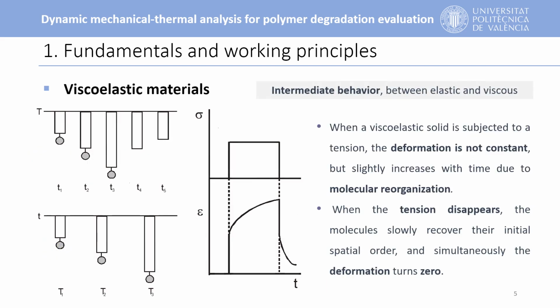Viscoelastic materials show an intermediate behavior between elastic and viscous performance. When a viscoelastic solid is subjected to a constant tension, the deformation produced is not constant but slightly increases with time due to a molecular reorganization induced by the applied tension. When the tension disappears, the molecules slowly recover their initial spatial order and simultaneously the deformation turns to zero.